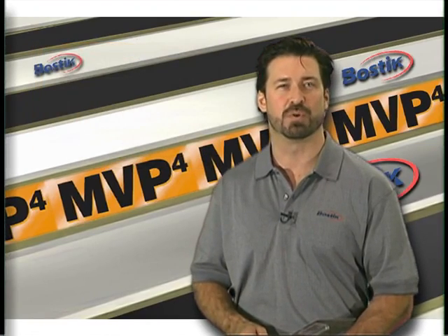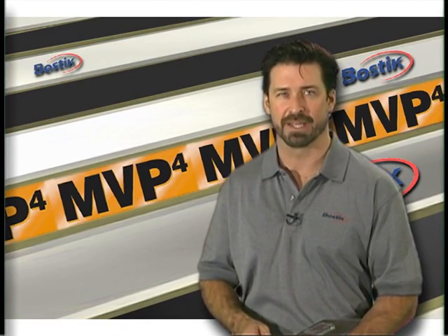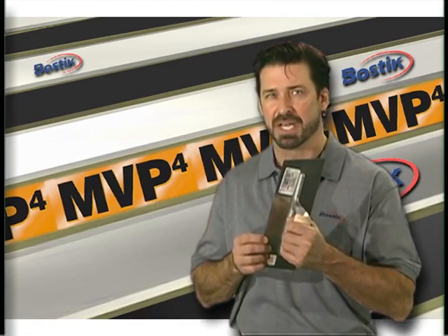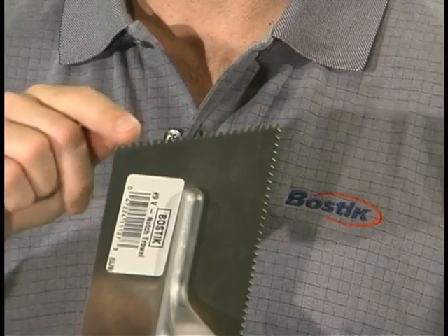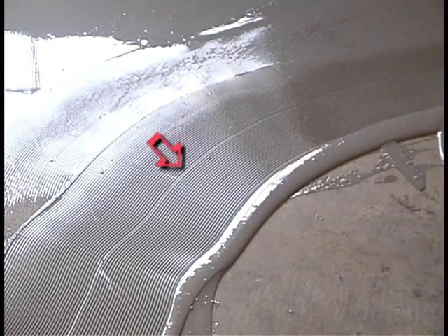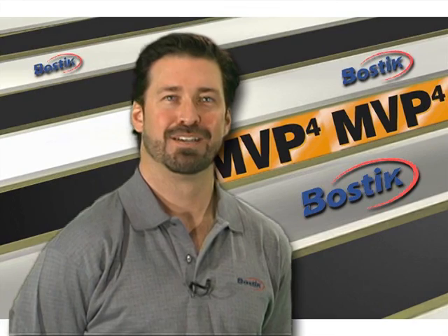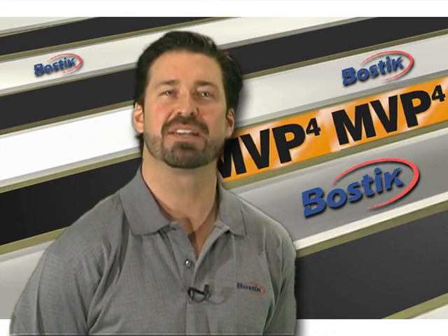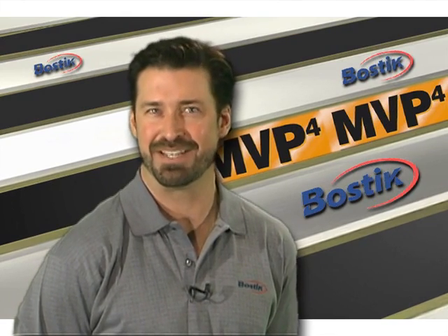This step is one of the most critical, and here's the reason why. The trowel recommended by Bostik for proper installation of MVP is a 3/16 by 5/32 inch V-notch trowel. Any debris, dust, or dirt on the slab that is bigger than the size of the trowel's notch will clog the opening and create gouge marks as the product is applied, since the debris won't flow through the notch smoothly. A clean and well-swept floor that has been vacuumed completely will help prevent installation problems and ensure an easy, quality application of Bostik's MVP.